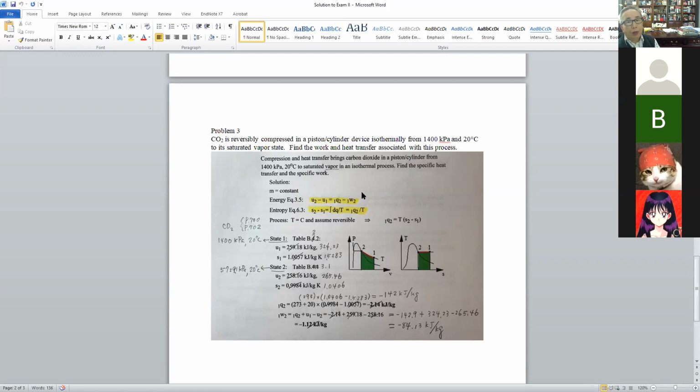Then first law for the closed system, very simple. This is ending state minus initial state equal to Q minus W. Second law, we already know for a reversible process, the change in entropy equals dQ over T. Once we realize this, if you can do these 3 lines, you get 50% of the points,